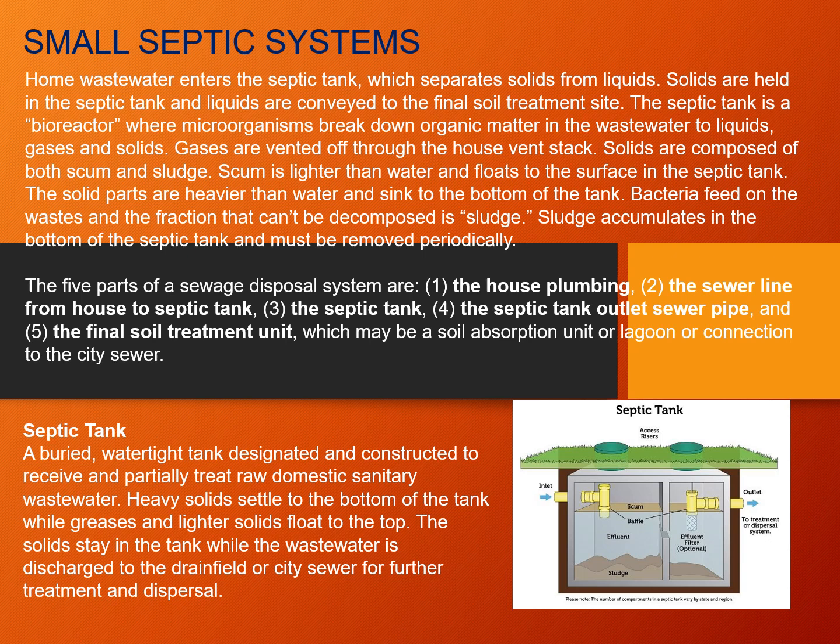The septic tank is what is called a bioreactor, where microorganisms break down the organic matter in the wastewater to liquids, gases, and solids. Gases are vented off through the house vent stack. Solids are composed of both scum and sludge. Scum is lighter than water and floats to the surface in the septic tank. The solid parts are heavier than water and sink to the bottom of the tank.